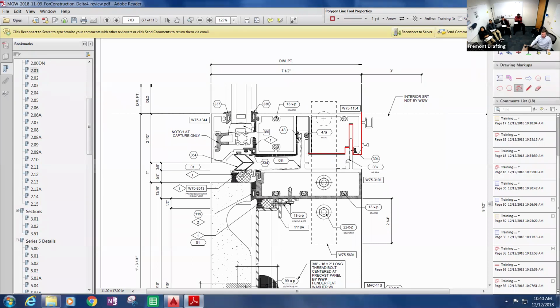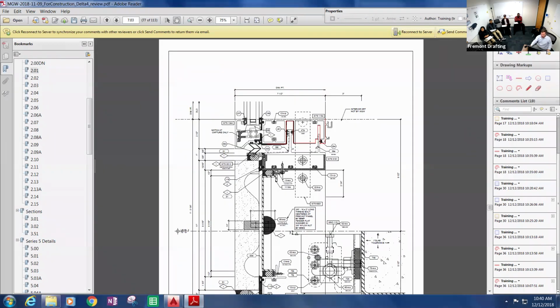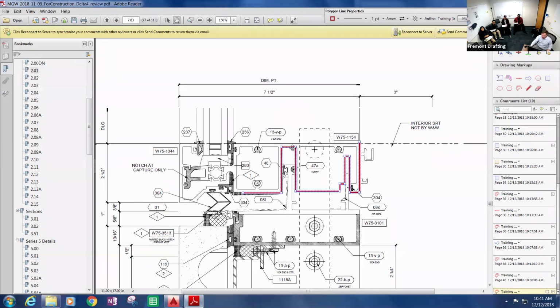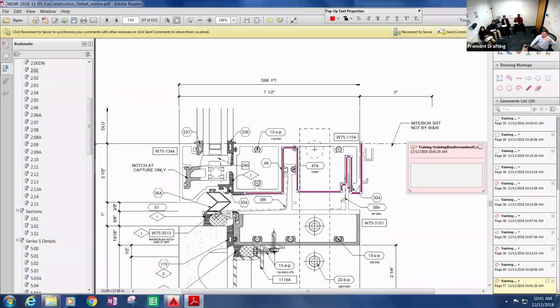So the dead load and wind load symbols that you were seeing on the elevations: this unit is dead loaded down here. The bottom of the other unit is transferring wind load through the chicken head. So this chicken head is actually what's taking the wind load of the bottom half of that unit. There's not actually a separate distinct anchor. And that's the notch that's allowing this unit to go up and down as the live load of the floor above goes up and down, or as the floor below moves down.